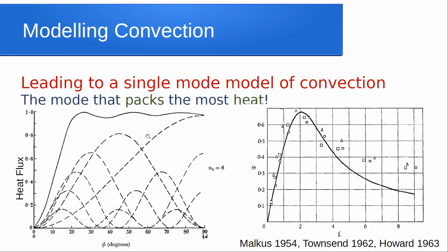What we'll be talking about is really just the fundamental mode, because we want just estimates of things. We're not considering the super precise estimates here. We want scaling, so we pick that one. And then what you're seeing on the right side are temperature perturbations as a function of distance away from the boundary layer. Here you have your boundary layer and your interior. And the symbols are measurements inside of a Rayleigh-Benard convection experiment.